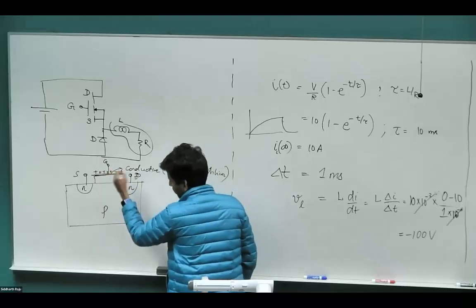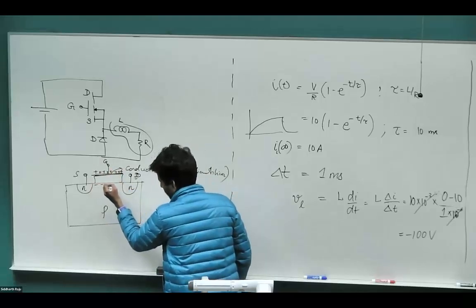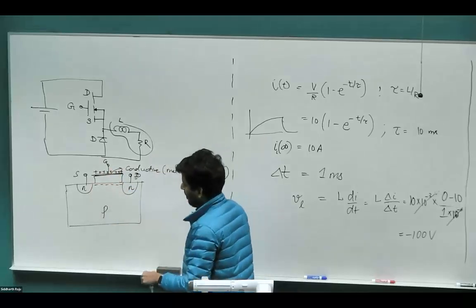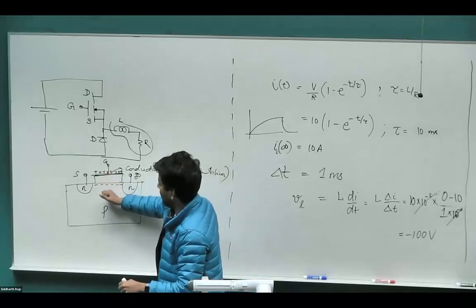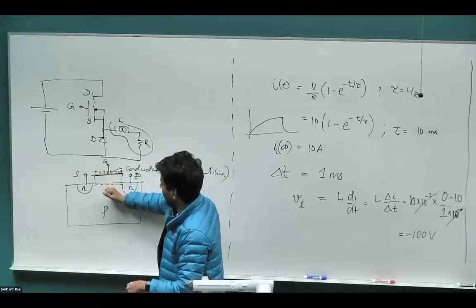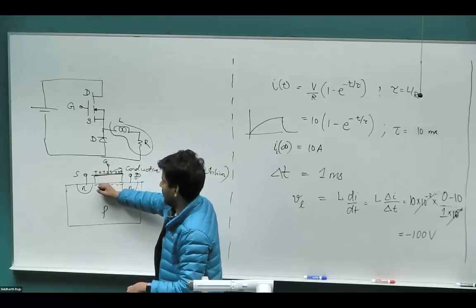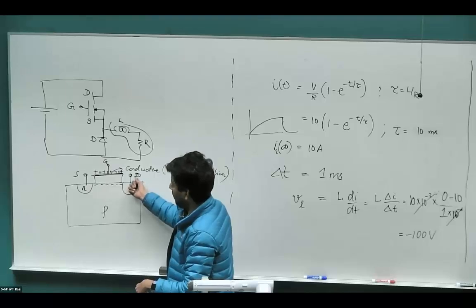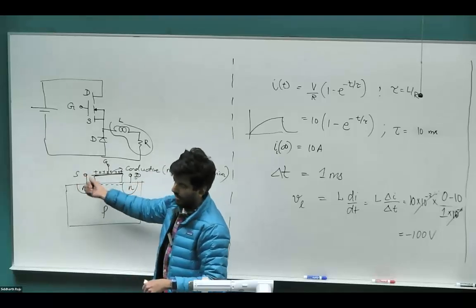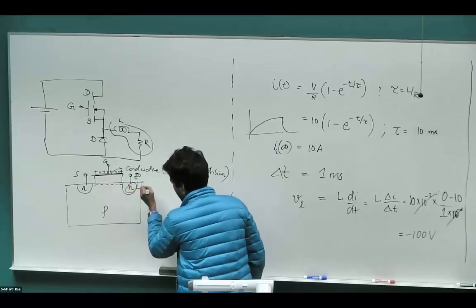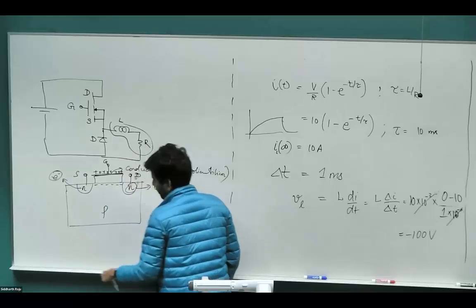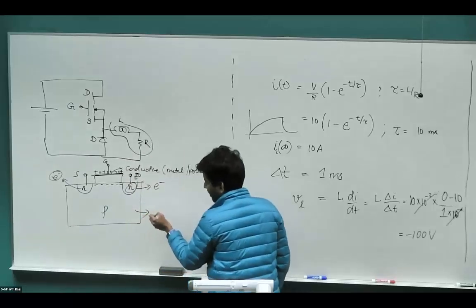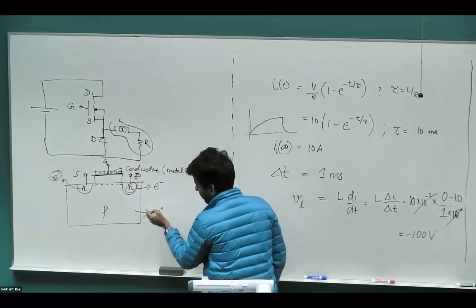Right? You apply positive voltage on one side, there's going to be negative charge that accumulates on the other side. And once you apply a sufficiently large positive voltage, crossing over what's called the threshold point, there would be a sufficiently thick channel here such that the drain terminal can now connect to the source terminal. Right? These N materials have a lot of excess electrons compared to the silicon substrate, and the P material has a deficiency of electrons, or you can just represent them as excess holes.